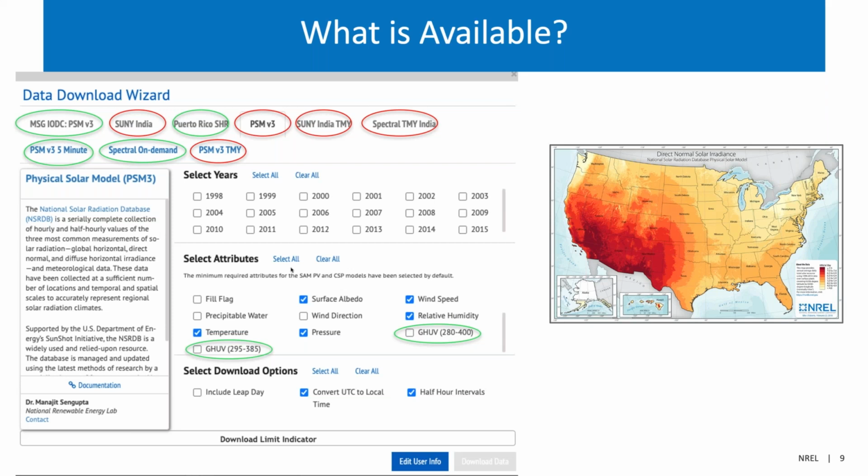So we've also, and there's a paper we published in Solar Paces, tried to identify times of the day or hours when it was all clear, like more than 90% of the ground data during that period of the hour was clear, and compared it with the DNI derived from the satellite. And what we found is that they match up very close.